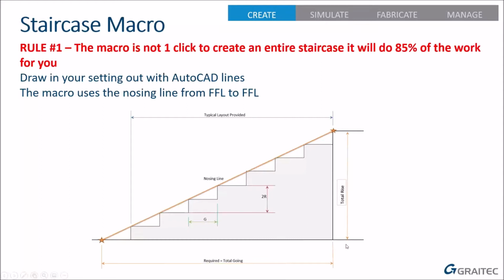If you're going just to steel beams and you're going to have a grating on top, remember to allow for the thickness of the gratings and so on when you're working out these points. Typically, though, the architect might give you the length of the stair to the front of the first tread. That's no use to us. Remember, we need where the nosing line is hitting the floor. So that's going to be an extra going on top of whatever the architect gives you to that first tread. It has to be where it hits the finished floor level, top and bottom, where I've put the stars.